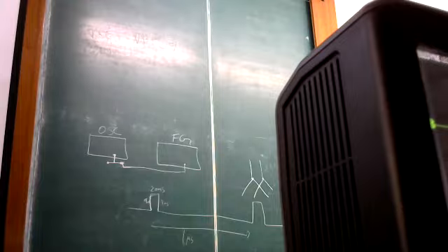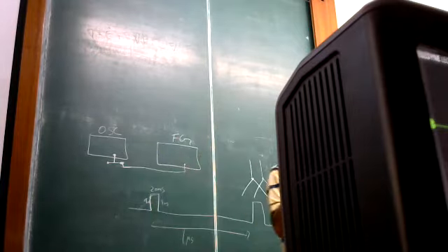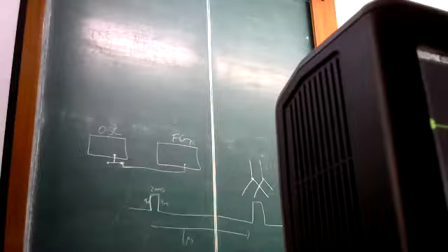What was I saying? 50 ohms. The load impedance ideally is 50 ohms, but because this is actually a low frequency instrument, both the signal generator and the oscilloscope we are using for this demo are on the lower frequency side. So it's possible to have electronics which has high impedance. The reason high impedance is always used is because if you go back to your ideal voltmeter picture, you want it to be infinite impedance so that it does not perturb the thing you are actually measuring. But at high frequencies in the microwave range, that's just not possible. This is low enough range that it actually provides you a setting.